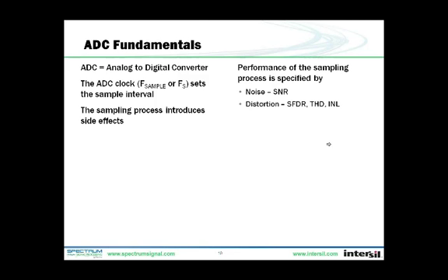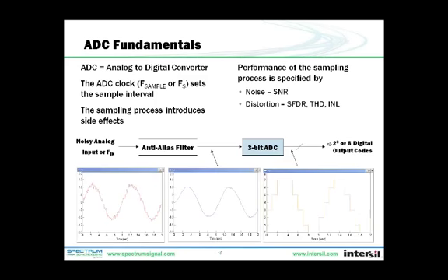The ADC will convert basically an infinite range of analog values into a limited number of digital output values. So there's going to be distortion because all the necessary digital output values don't exist for this infinite input range. Additionally, the ADC will have non-ideal performance, so even more distortion can be introduced. Noise is going to be another problem because the ADC will have a limited range from the largest signal down to its noise floor.